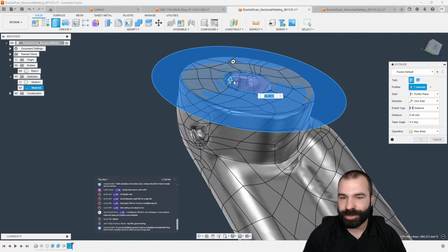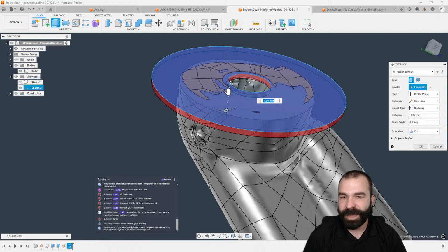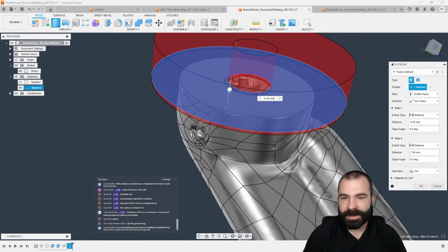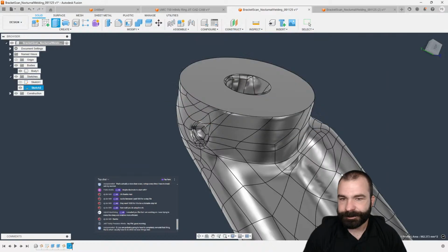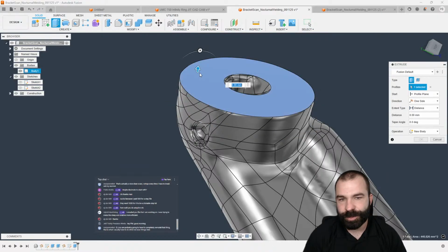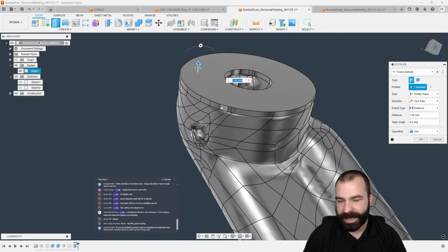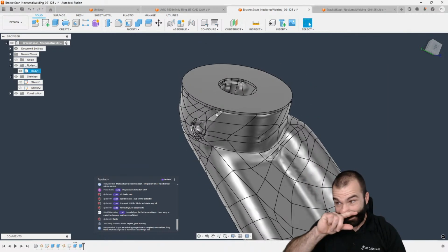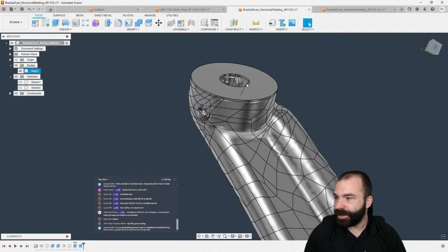I can now extrude that outside profile and flatten out that surface, whatever I need. Again, we'll go ahead and go 2 sides this time. Pull this one up. Pull that one down, whatever it is going to give you the flattest surface possible. And then again, you could come back with like a normal extrude back up the other way to bridge that gap back in.